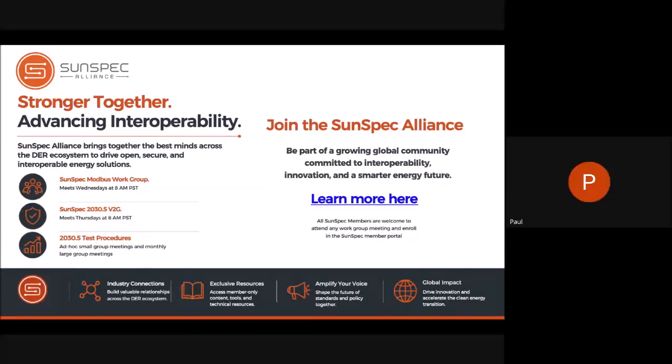I'll give a hypothetical, just to test myself here. So I work for EG4 and there's Tesla. Conceivably what could happen is you have both of them in a network, and in a power failure, the handshaking we're talking about here is one of them becomes the master that controls the other one. Correct? That's correct. All right, so I get it now. I can speak for the EG4 inverters. There is a handshake between parallel inverters that does that. It's very proprietary, absolutely bespoke. But it works. But what you're saying is if you have multiple sources that want to participate in this island, this is how they would communicate. And you would have to establish in the programming who is first online.